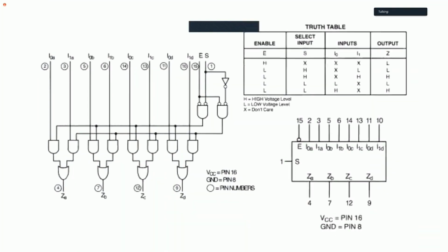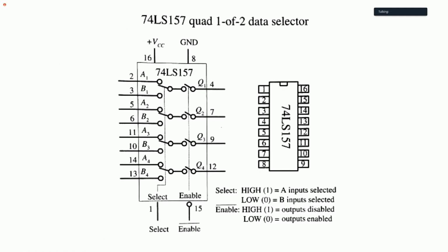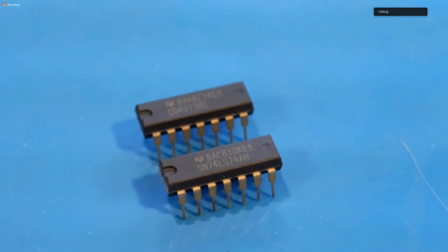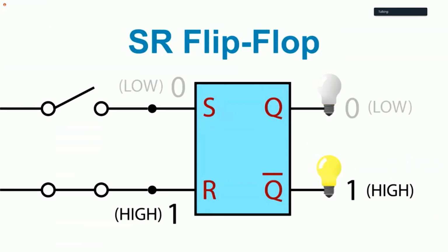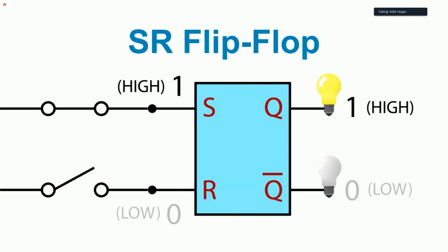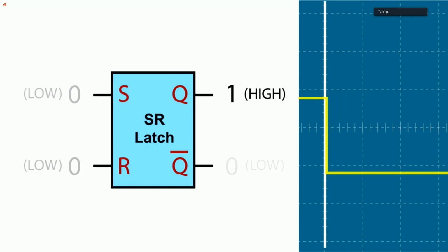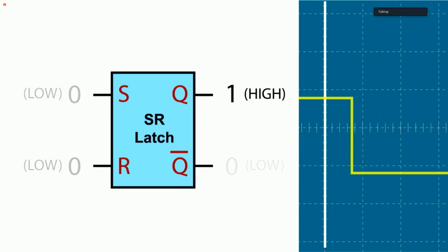Our last lesson was about multiplexers, demultiplexers, encoders, and decoders, combinational logic devices where the output is dependent only on the current state of its inputs. Flip-flops, or latches, are sequential logic devices which have a form of memory built in. This means they can use not only the data from their current inputs, but also previous data from their inputs and/or outputs. Flip-flops are bistable devices, meaning their inputs and outputs can be at one of two states, a logic level 0 or a logic level 1.